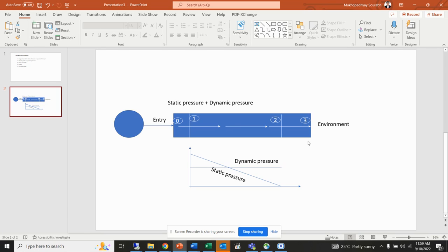So at that time the code will understand, stagnation pressure is zero, so static pressure will be negative, and because there is some suction, dynamic pressure will be positive. Okay, so that's why the static pressure will be negative but dynamic pressure will be positive. And due to that strong dynamic pressure, the code will understand that this is the outlet boundary condition, the strong dynamic pressure will suck the flow, and it will go through. This is called the outlet boundary condition.